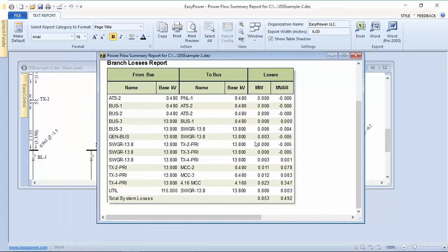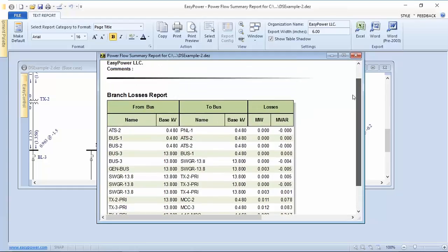Although what we've done with this import is override the motor load parameters, we still may have errors in our data collection when we did the study in terms of what the cable impedance is, the cable length, the number of conductors, and a lot of the elements that won't necessarily show up on the SCADA file.